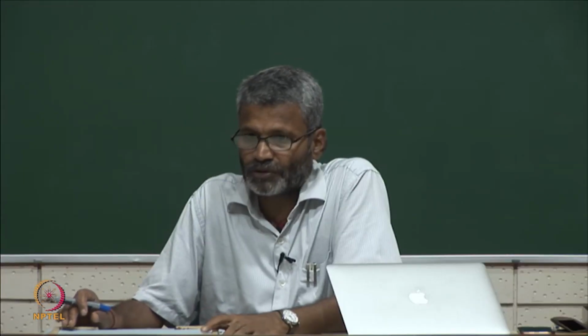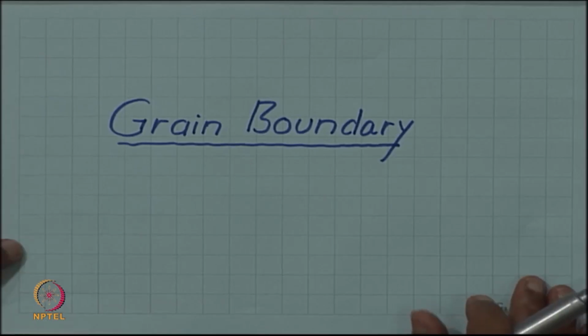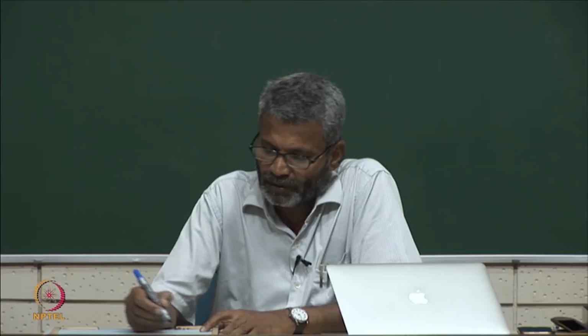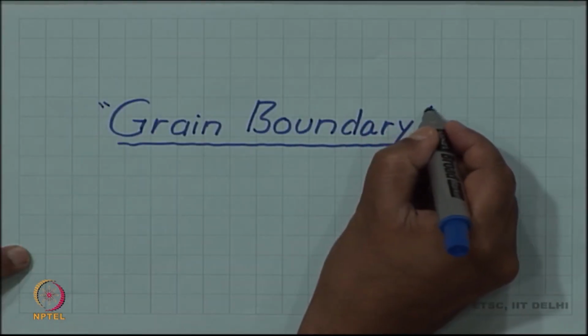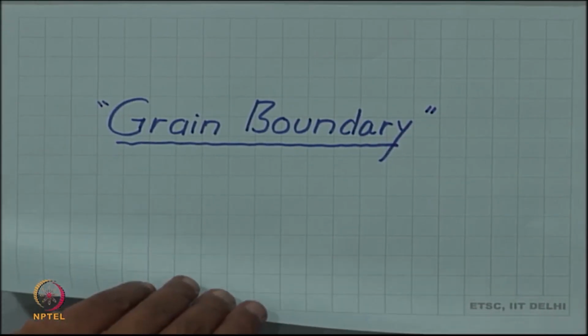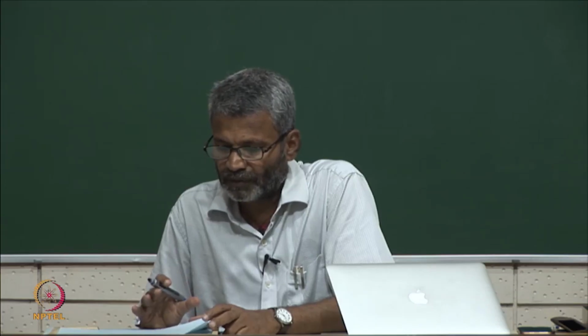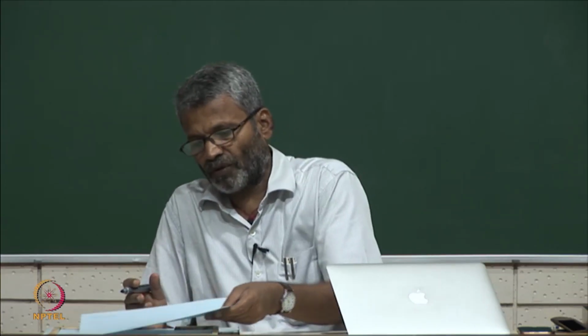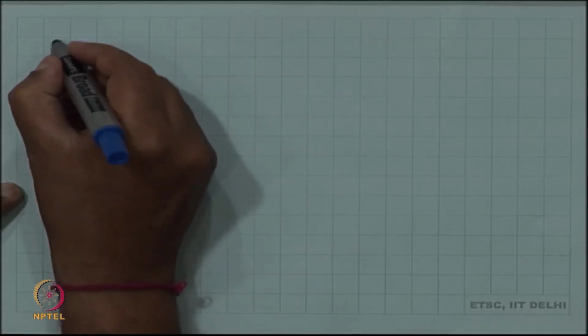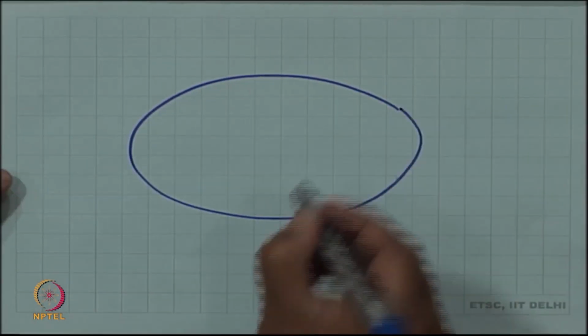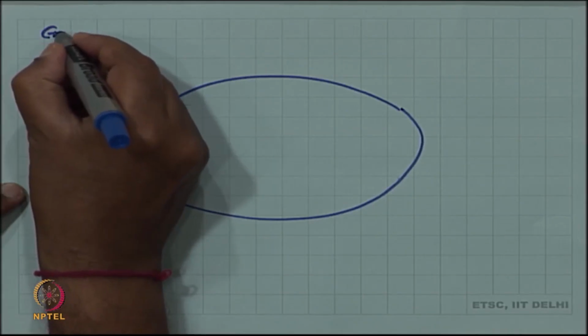We continue our discussion on two-dimensional surface defects, and one of the important two-dimensional surface defects is the grain boundary. Grain boundaries are internal boundaries inside a crystal, and we have already met them while discussing dislocations, because we said that dislocations inside a crystal can end on a grain boundary. So, a grain boundary is also one of the locations where a dislocation can end. When discussing that, we drew a picture something like this, suppose this is a sample, we are trying to indicate a grain boundary.